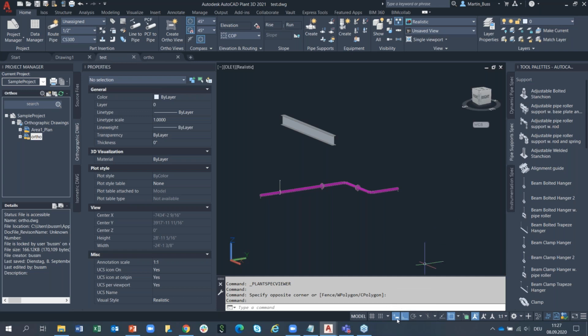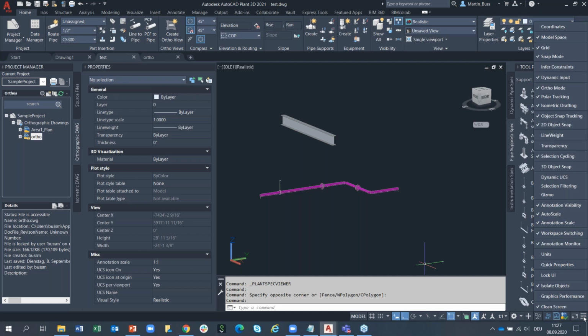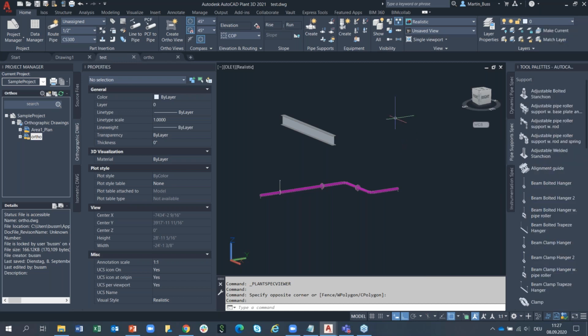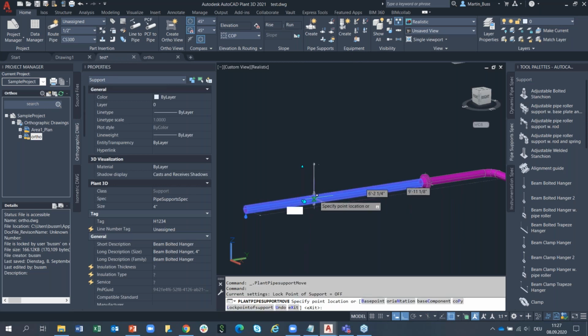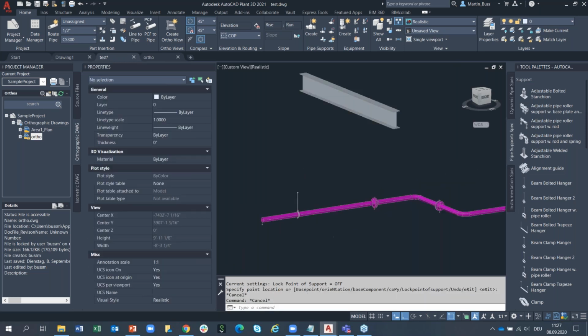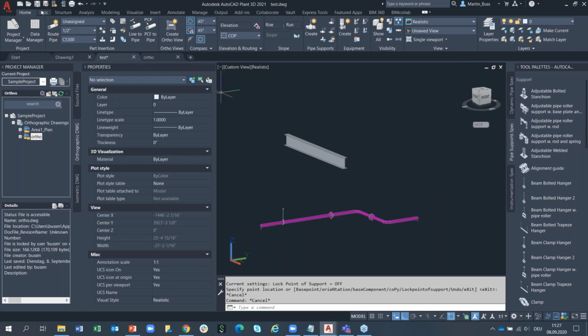And just in case you don't find it, it looks like this: dynamic input on here. In case you don't find it, then it's not activated, and you have to activate it by clicking on this sandwich symbol here and then going up to the dynamic input and enabling it. Enabling means it's there on the bar, but then you also need to activate it in order to use it. So as you can see, for example, if I move this, now it will offer me the dimensions, and I can jump with the tab key between the particular dimensions in order to reach them and change them.